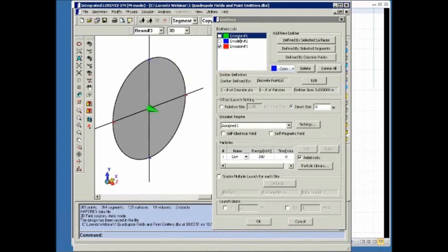The first emitter is a point emitter right at the center, launched down the optical axis. The second emitter consists of 2 points, and those are on the axis which is focused by the first quadrupole. And the last emitter that I've defined has 2 points, and those are on the axis which is defocused by the first quadrupole. So now I'm going to add some segment emitters.